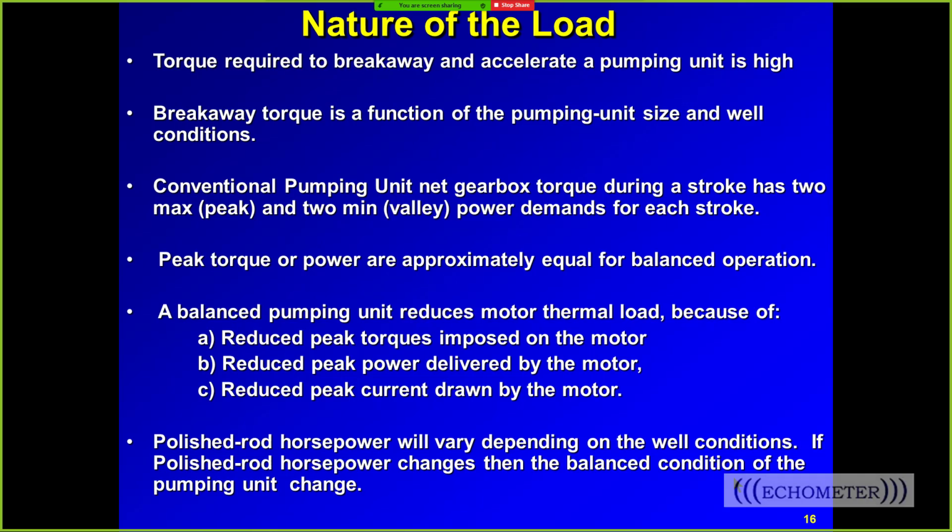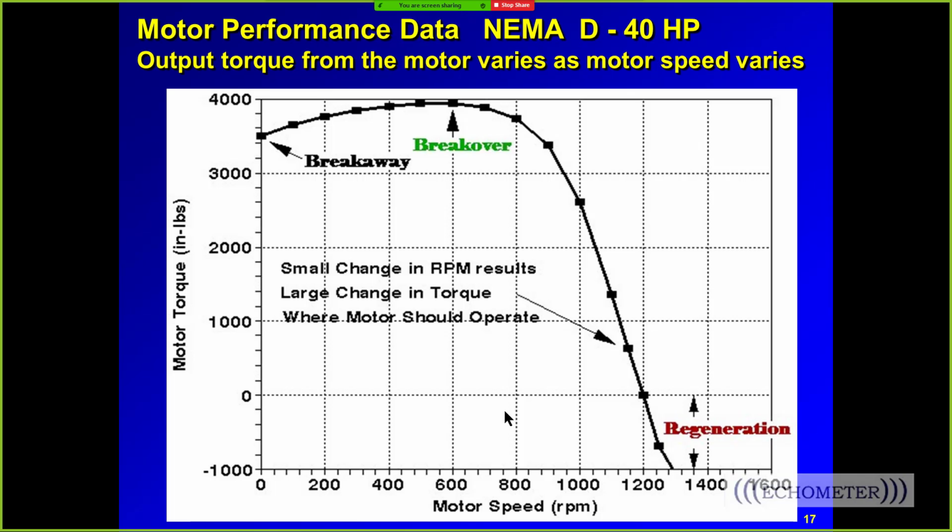So in some fields, you have to move the weights when you first set the well up because you don't want to cause damage. And then it may take a long time to draw it down. And once it gets drawn down, you may have to move the weights again to prevent overload. So this is important. And if you don't do that, then you can damage your pump unit and reduce the life of the gearbox. This is a plot from some Robbins & Myers motor performance data versus RPM of the motor.